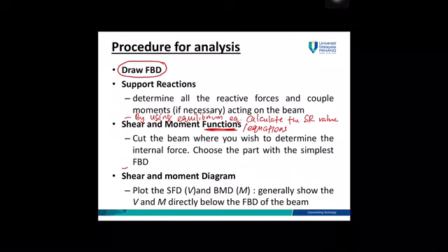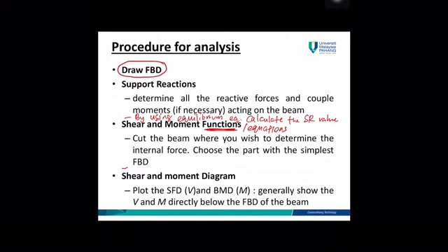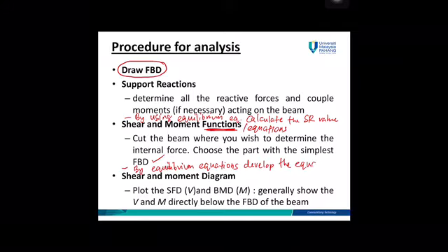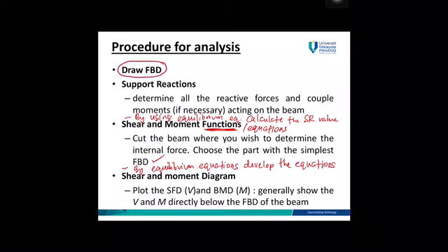How to develop the equation? So you need the free body diagram and also the equilibrium equation. And then when you have the functions or the equations, you can plot the shear force and bending moment diagram.